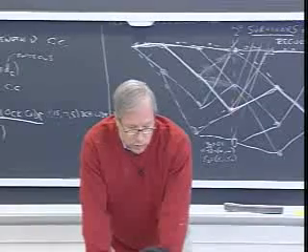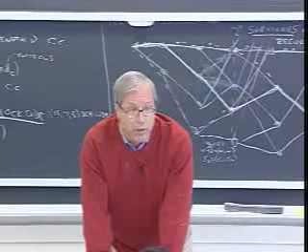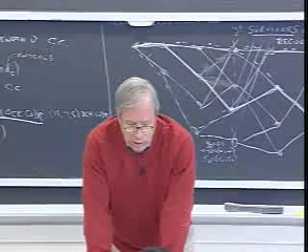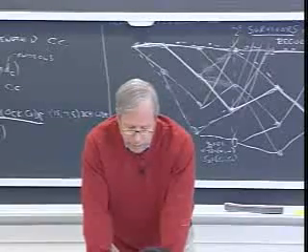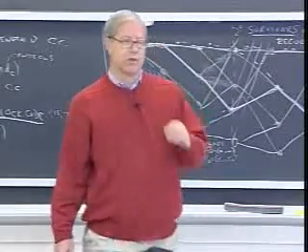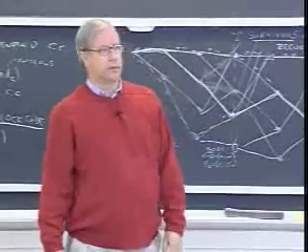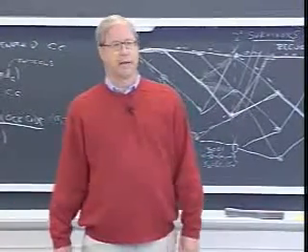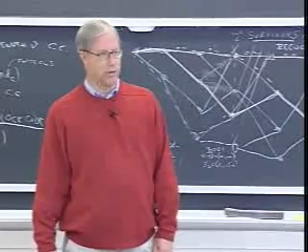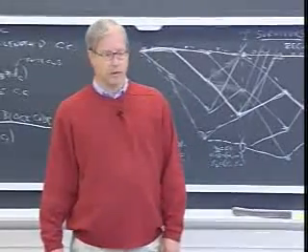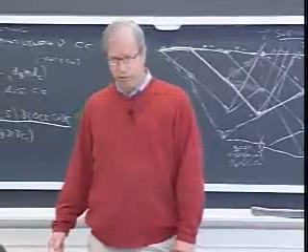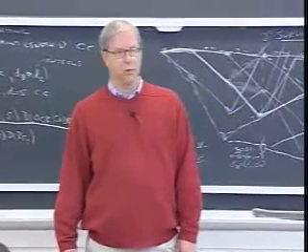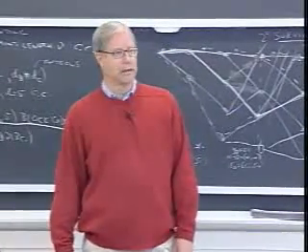First person to do this was Jerry Heller at Jet Propulsion Laboratory, again about '68, immediately after Viterbi proposed his algorithm in '67. Heller was the first to go out and say, well, let's see how these perform. So he found a good 64-state rate 1/2 code, and he did probability of error versus Eb over N0, and he said, wow, I get a 6 dB coding gain.